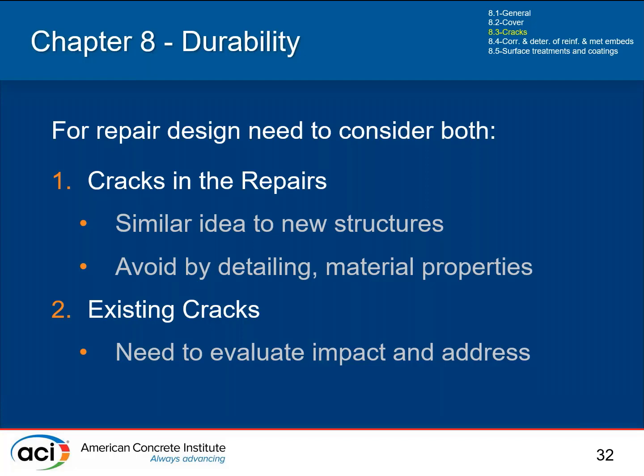Getting the right material properties, getting the right compatibility. If I could call back to what I talked about earlier, the right bond, lower shrinkage, those kinds of things. That definitely needs to be considered. But also the existing cracks can't be ignored. Some of them will go away when you do your repairs.